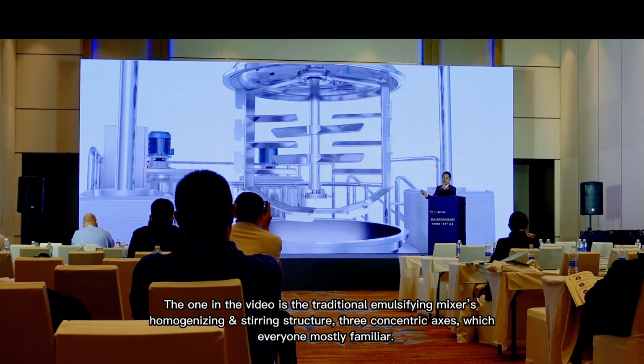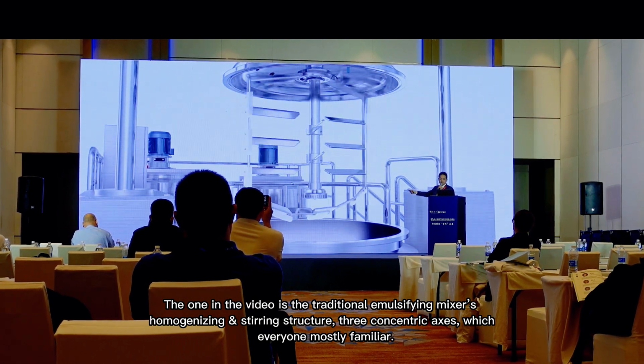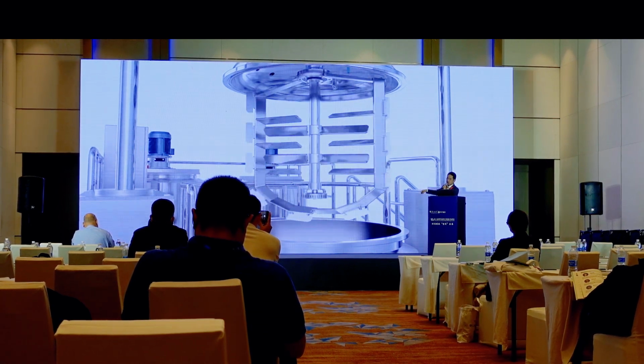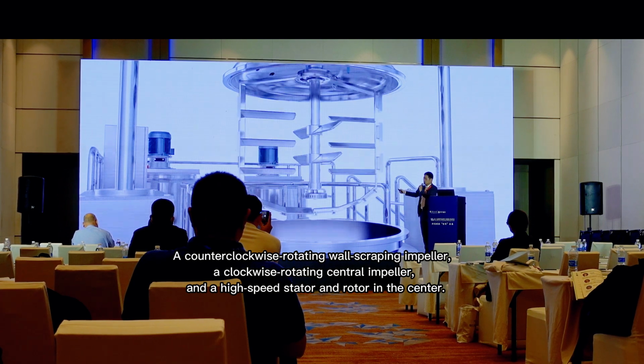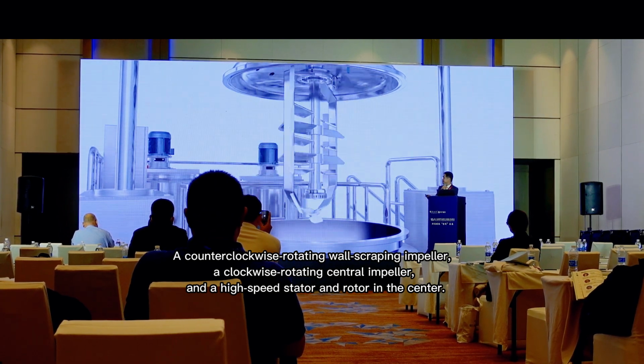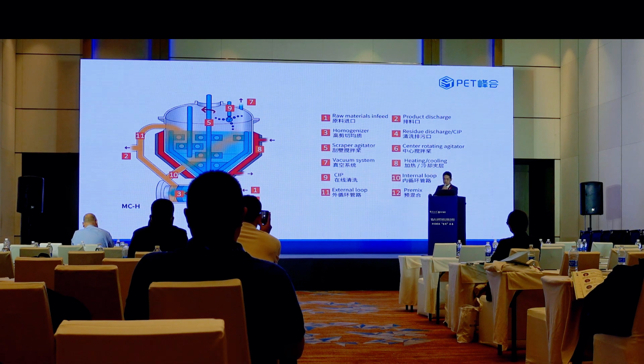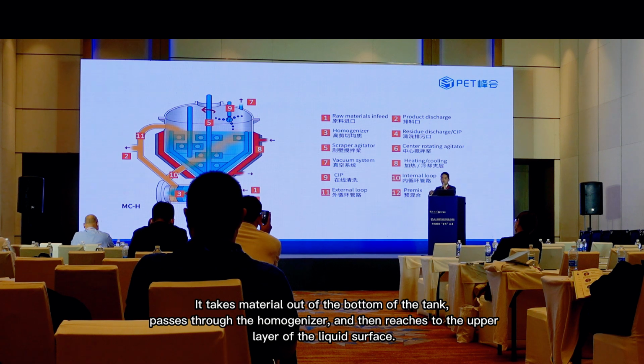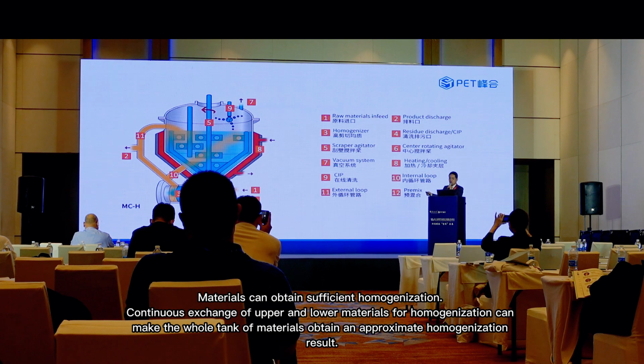The one in the video is the traditional emulsifying mixer's homogenizing and stirring structure, with 3 concentric axes, which everyone is mostly familiar with. A counterclockwise rotating wall scraping impeller, a clockwise rotating central impeller, and a high-speed stator and rotor in the center. The homogenization method adopted by the 5th generation emulsification technology avoids blindly stacking time. Materials can obtain sufficient homogenization.